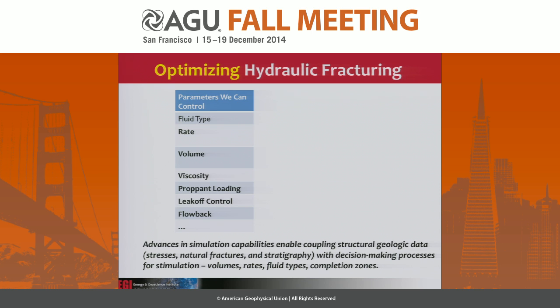And in terms of our fracture designs, these are what we're looking to be able to manipulate to come up with a hydraulic fracture and subsequent production that is actually effective. And so these things, as we can see, we have room to vary the fluid type that we're using, the viscosity of the fluid type, whether or not it's a compressible fluid, whether it's a water-based or sometimes even an oil-based fluid, the rate at which we pump, the volume that we pump, and our mantra these days is that we pump more and we pump at higher rates.